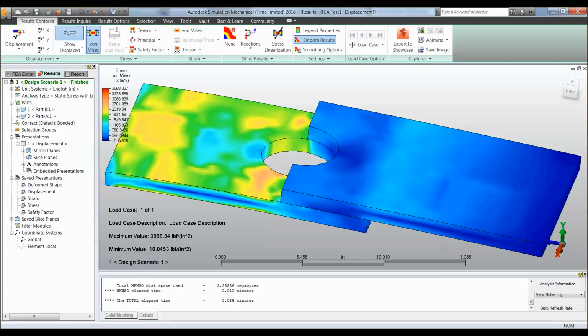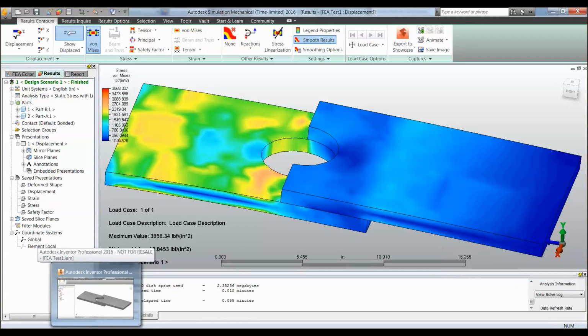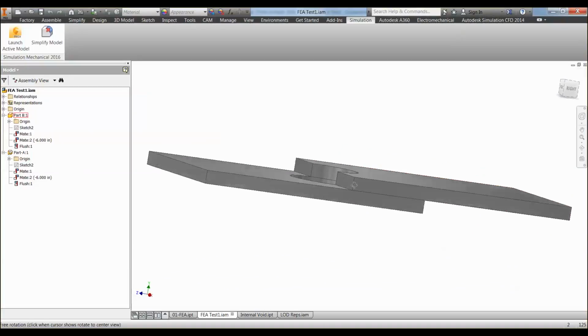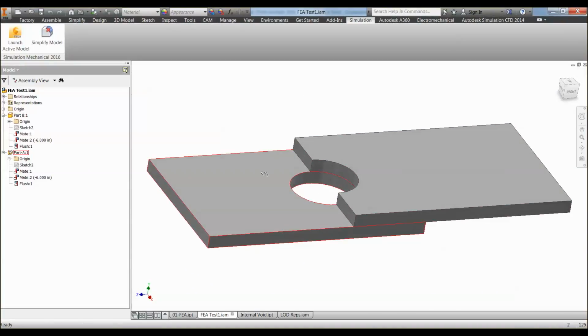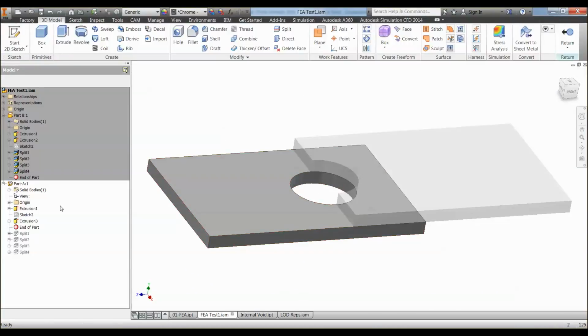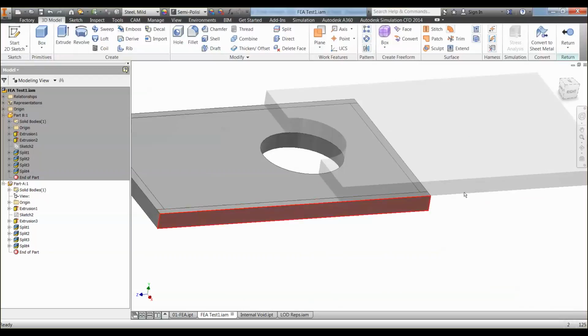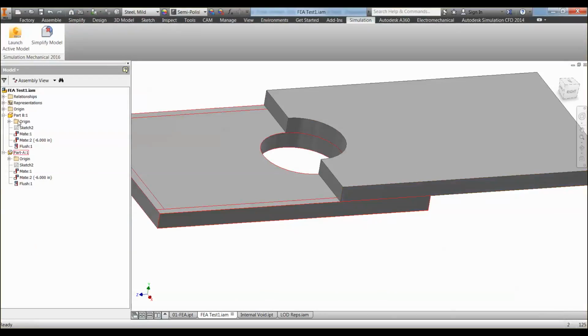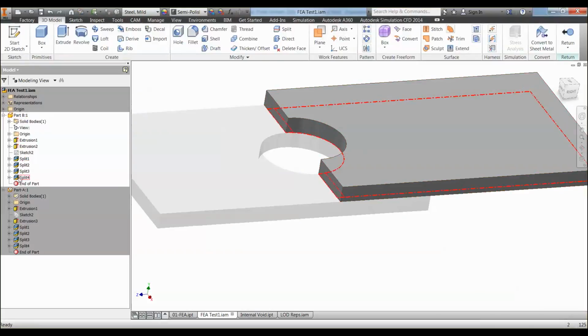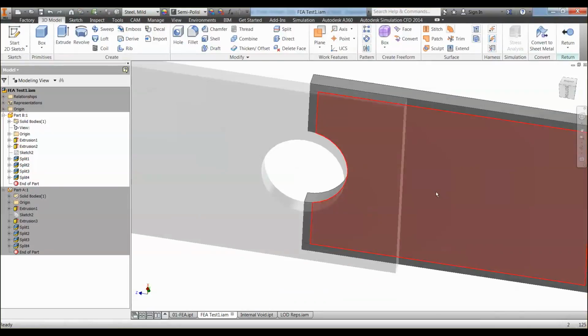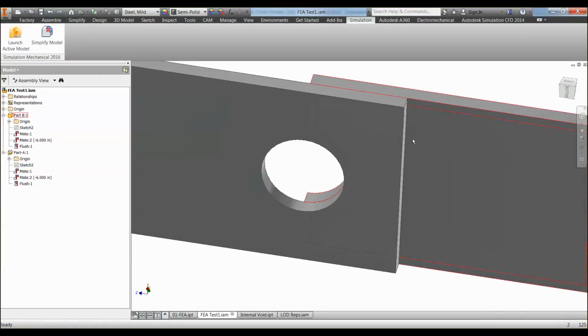Now, if we want to represent this a little bit differently in there, we can actually go back to Inventor and do a little work with the split surfaces in there. So jumping back to the split tool, in these parts I've got these already predefined in here. I've got this stepped in so that I know how far I want my weld to go in. We can have those set up in there, and same thing on this part, have splits set up on that side.